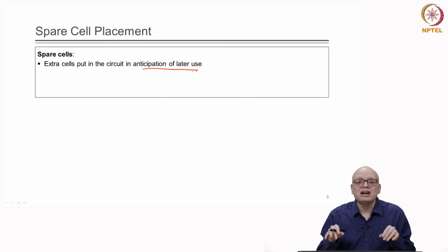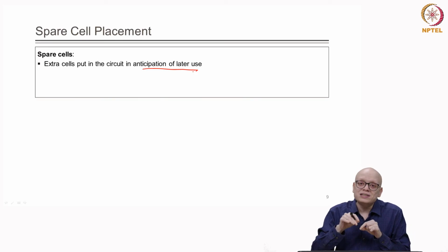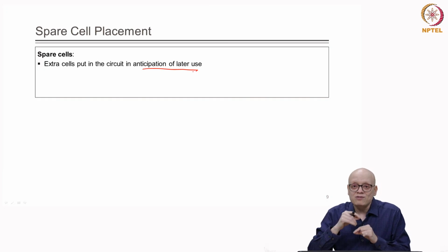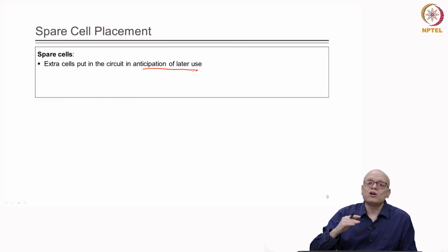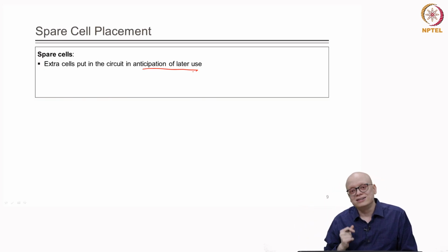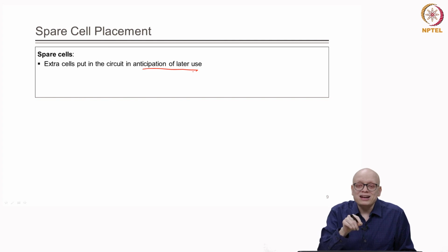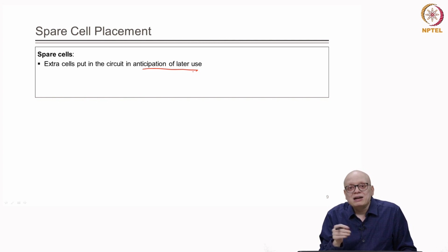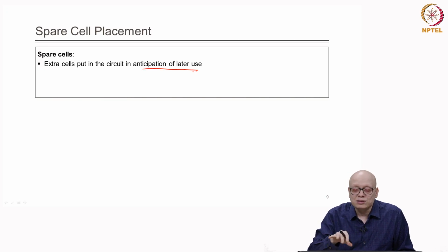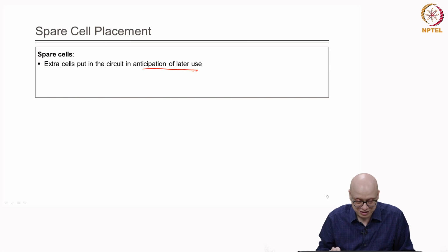Only what we need to do is make some changes in the interconnections or rewiring of these cells, and that can be done by just making changes in the topmost few layers of the interconnects. Therefore, the cost of respin can be reduced if we find spare cells in our design which are not used, but later on when a bug is found we can use them and those cells can deliver the functionality.